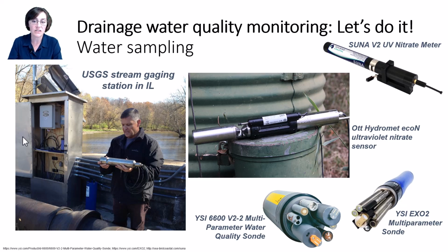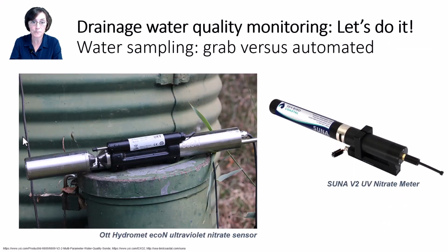Real-time nitrate sensors don't actually involve sample collection and sample analysis. Rather, they use technology like in situ ultraviolet spectroscopy to generate nitrate concentrations in real time. The downside of these sensors, obviously, is their capital cost. Each sensor, plus all the associated parts and pieces for logging and streaming to the internet and data plans, etc., are on the order of $10,000, $20,000, even up to $40,000 apiece.